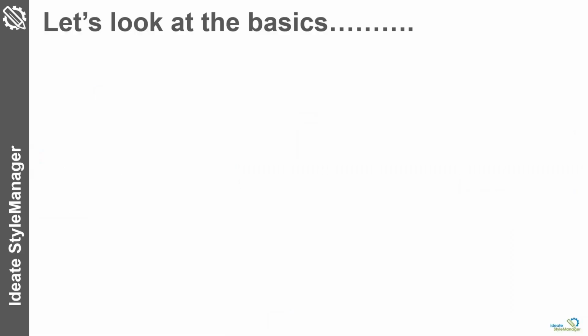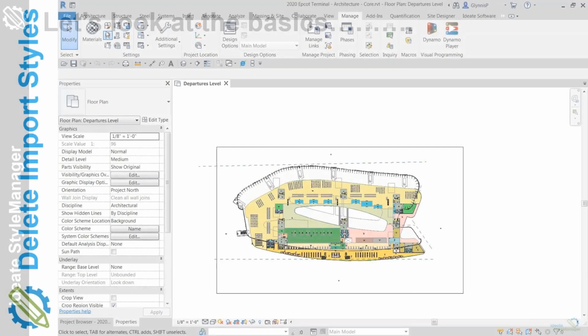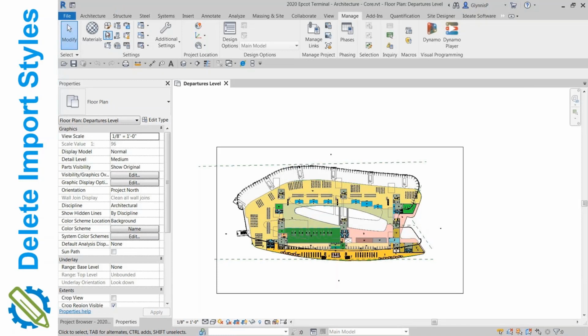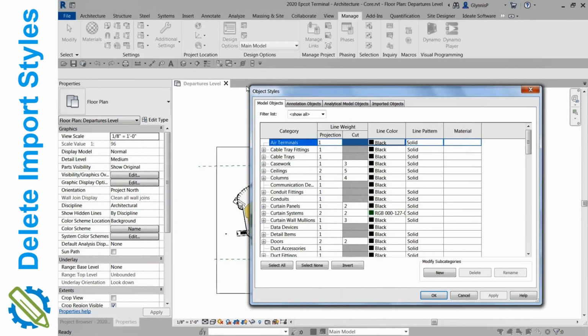Now that was just looking at, like I said, linking in kind of a basic AutoCAD file, but there are times when it's even a little bit more complicated, because what you're doing is you're linking in content like a family, and then that family may have, let's say, AutoCAD linked into it. Like a good example is a title block. You may say, oh, I'm going to take this title block RFA, I'm going to bring it into my project and everything's fine, but all of a sudden you're getting all these styles that don't match your standards. It may be because that particular title block had within it a nested family that might have a symbol that came from AutoCAD. So we can review all that information.